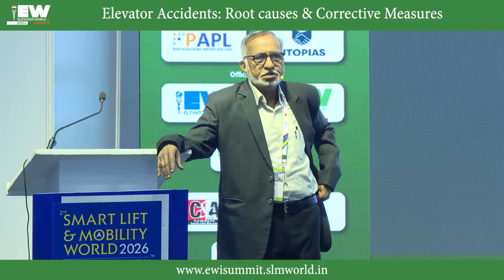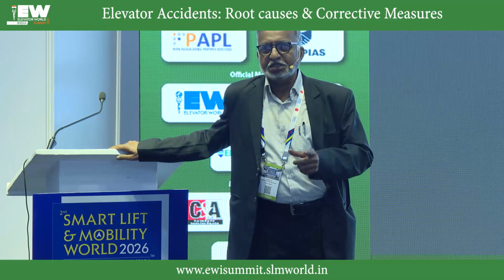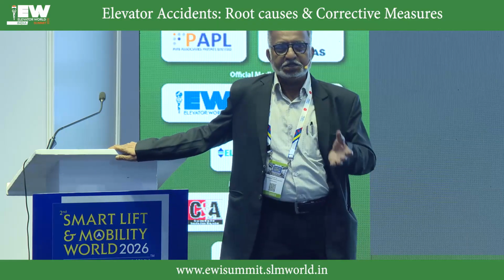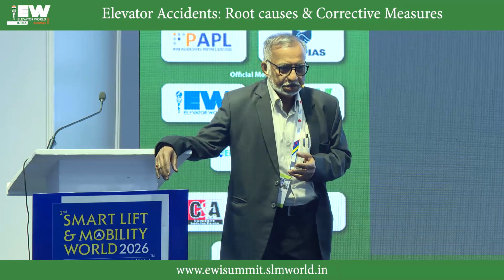Then, if one gets injured during door closing operation, who is responsible? Now, if the person gets injured when the door is getting closed, who is responsible? He himself is responsible because he is not aware. But I will say it is the technician or the company who is responsible. Reason? Because he has not trained the users. If you are having a lift in a society, your duty is to have regular safety training for the users. They must know what is to be done, what is not to be done. So you have to have frequent training, at least twice in a year.